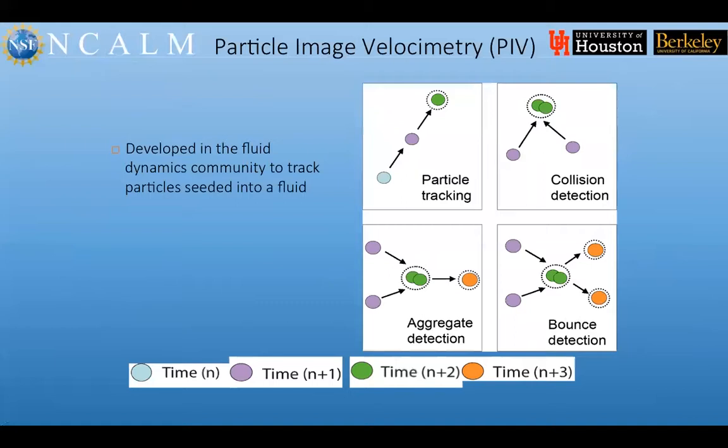So you want to look at turbulent flow, you put a whole bunch of particulate in, and you take a bunch of high-speed pictures of that particulate, and you want to track how those particles move so you can get an idea of how the turbulent flow is progressing. And so they have some terms that they use within there. The piece of software that we're going to be using in MATLAB, PIVlab, was actually part of a PhD thesis developed by a student who wanted to track the flapping of bird wings, which has nothing to do with the glacier that we'll be looking at.